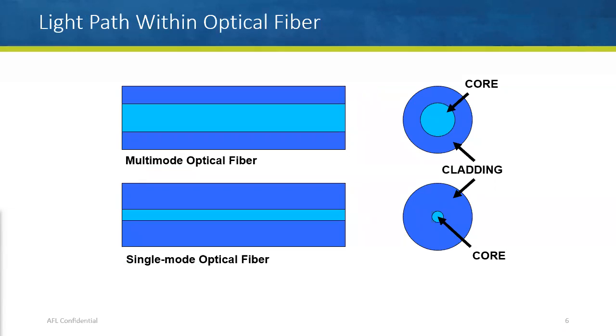So yeah, I think I'm gonna try to answer this one live. The single mode versus multimode. Basically, the differences of the core size on those, and that core size gives you a big difference in how the light travels through. And so with the larger core multimode, the light can bounce around as it's going through, which gives you some limitations that we're going to talk about.